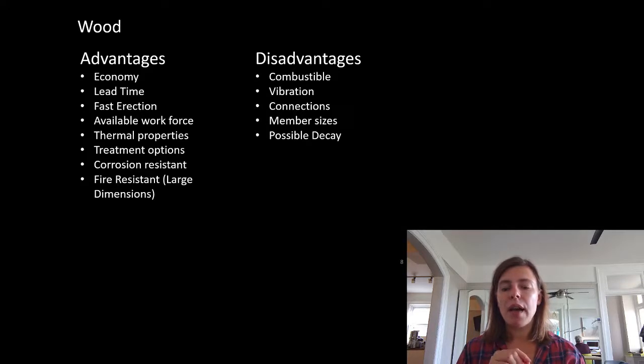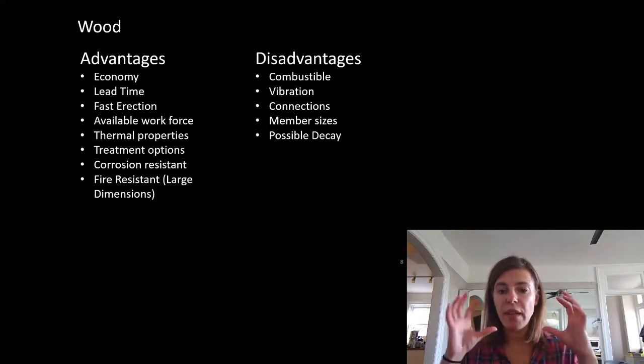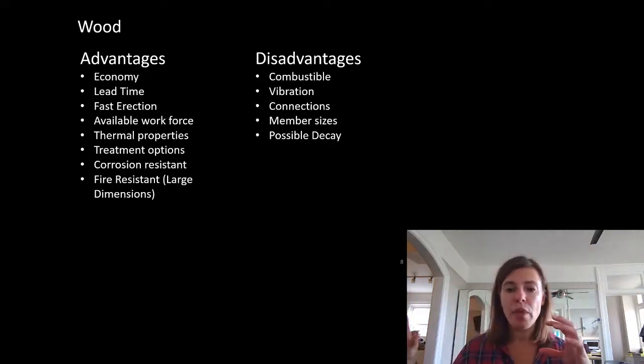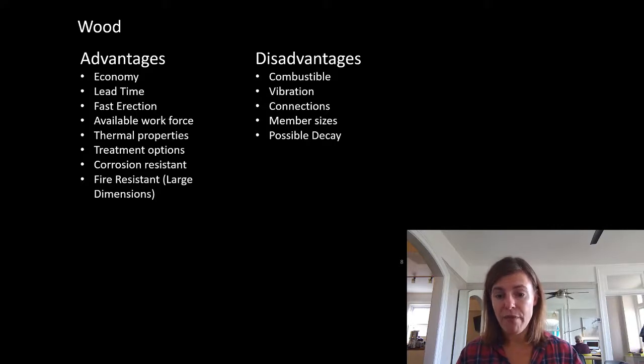At 1 hour of a burn, you're not worried about a full assembly load in your building. You're not worried about 4.8 kPa of people jammed on that floor. You're down to 1 kPa or 0.5 kPa, a very light load for those last people that need to get out or the fire department coming in to help extinguish that fire. There's enough material left to resist that load.